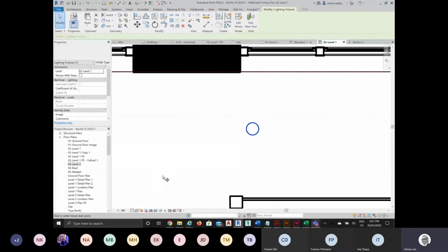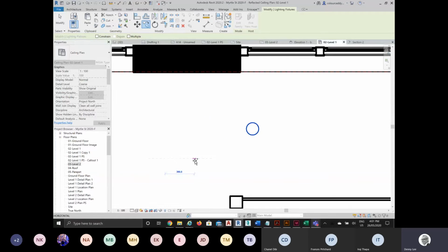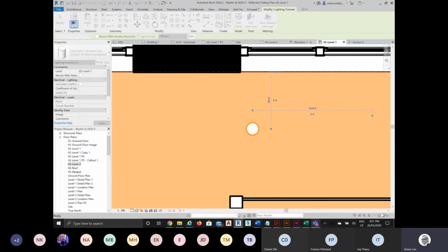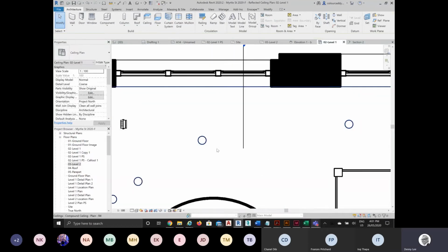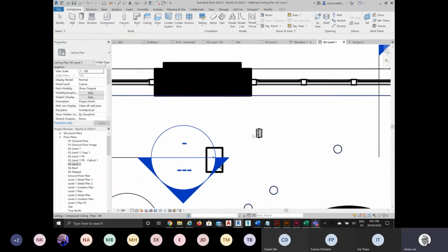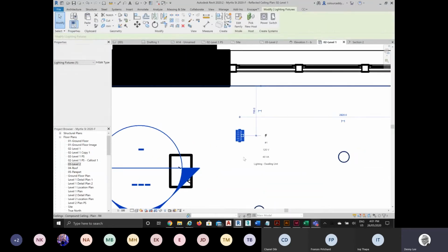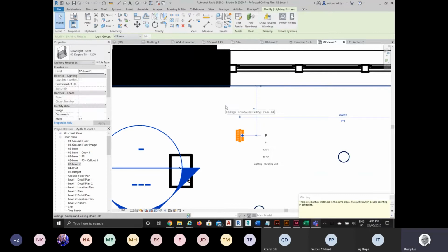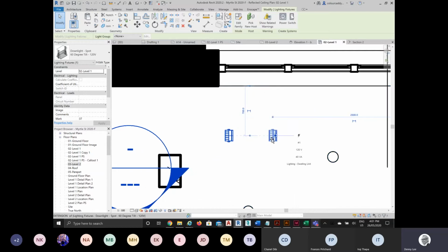Okay, so unfortunately I can't show you the issue that you will have, which is that basically when you go to copy them, even though you might choose 2 points, it'll come up like that. So it'll tell you either that it can't create the second one, or that they're identical instances in the same place. So here, I'll do it again with this one. So if we go copy, and again, you try to click 2 points. And you may get this warning where it'll tell you there are identical instances in the same place. Now, that's actually not such a problem, because then I can just drag one of them away, and that solves it.